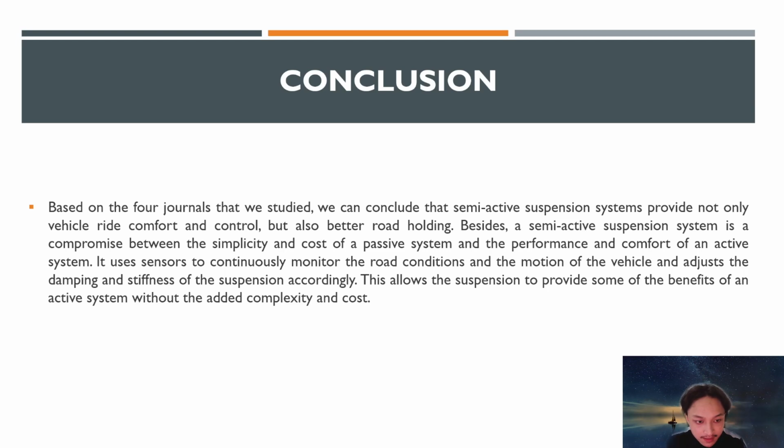It uses sensors to continuously monitor the road condition and the motion of the system and adjusts the damping and stiffness of the suspension accordingly. This allows the suspension to provide some of the benefits of an active system without the added complexity and cost.